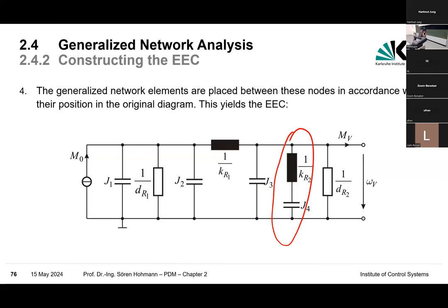My colleague Thomas Leibniz said, well, yes, mechanics is stupid because there is exactly one frequency I can cancel out. That's difficult. Why not take the generator, attach additional power electronics to it, and drive the generator in such a way that the generator cancels out the frequencies? And this works also. You can do generator-based frequency damping in that way.